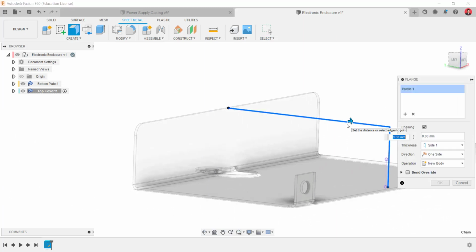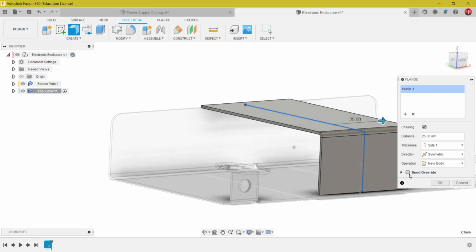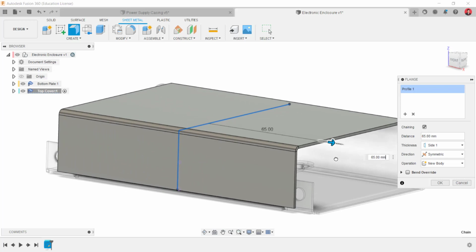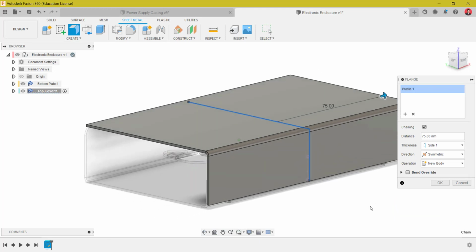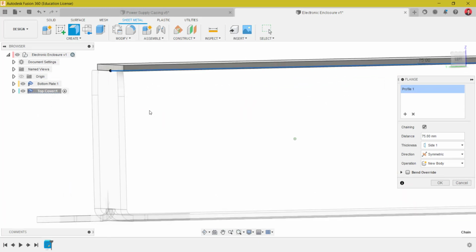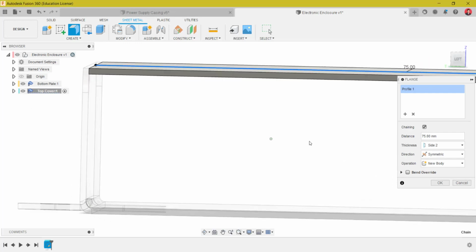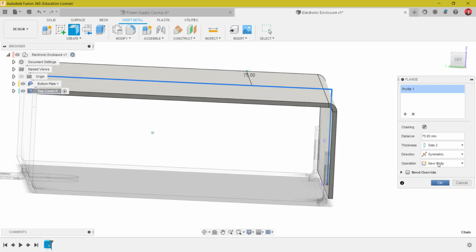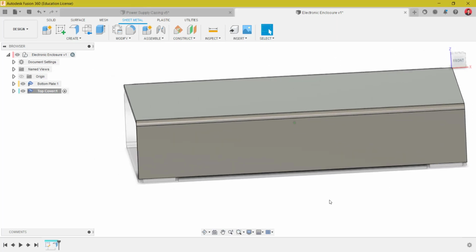and use the same command, which is flange, and choose the symmetric plane and just extrude with the 75 value, so both sides have the same length. Okay, I will use the slide tool in order to make it flush from the top position, and also flush with the bottom plate.